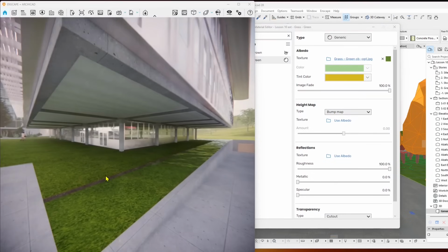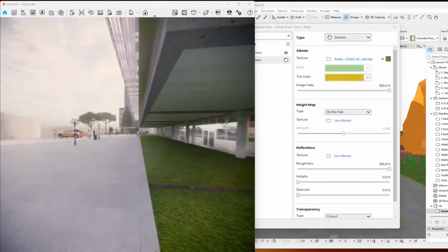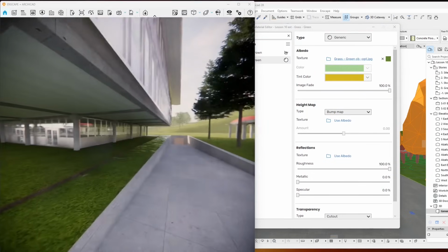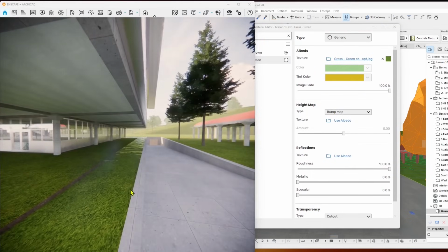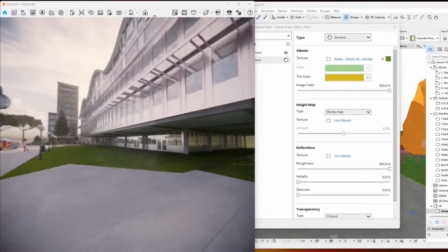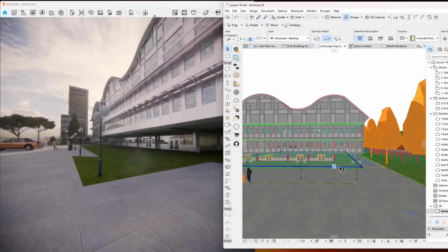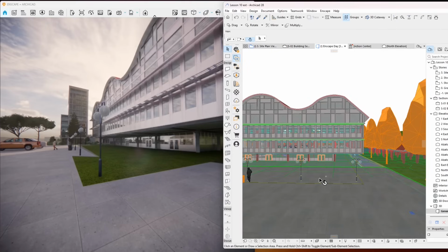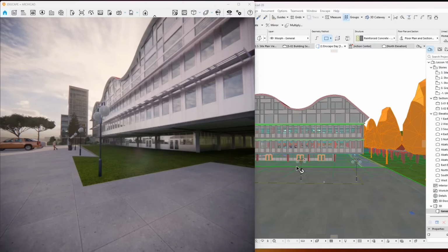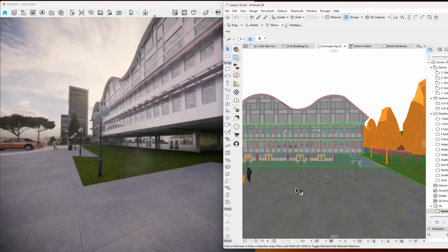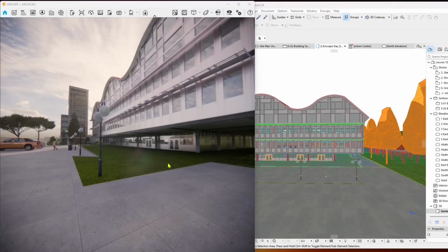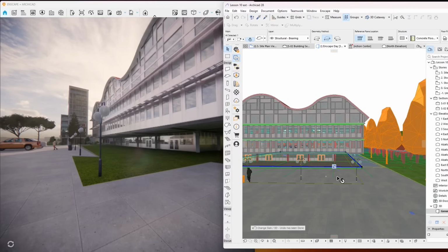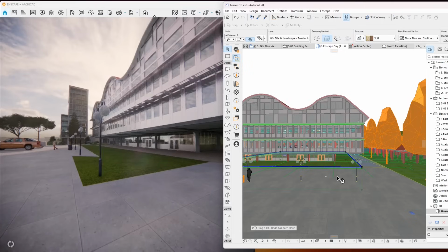Now, flickering happens when you have perfect overlapping of two surfaces. So to avoid that, just move the surface either higher or lower. So right there, we have a kind of a strange combination of grass and water right now. So let me just use another surface so we can see it better. So I'm going to go back, Control Z, and readjust that to avoid that flickering because I've moved those surfaces and they are overlapping. So if I go back, Control Z, I fix it.